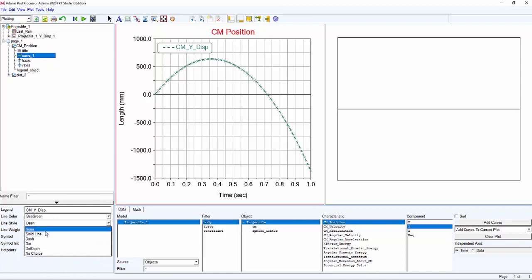So here I'm going to use a solid line, and as you can see, the symbol appears right here. If you are using X, you can use circles, you can use dots, or you can choose the ones that will fit with your application. When you have too many points, the symbols are going to overlap, so you can add one symbol every five points like this. So you have here after 5 points, after 5 points, and so on.